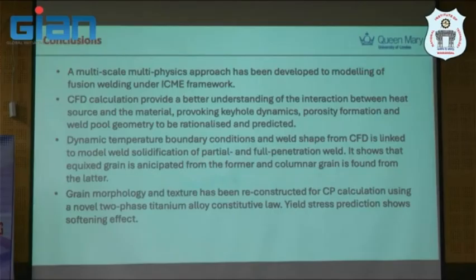And it shows that equiaxed grains actually form in the conduction mode and the columnar grains mostly in the keyhole mode. Again, this one is carefully observed in the condition we know very well. So this nucleation condition, I think, is varied to assume, but for additive, it's so dynamic, so kinetic. So we need further study to confirm what is the real condition that represents the process. I believe it varies from material to material, condition to condition as well.